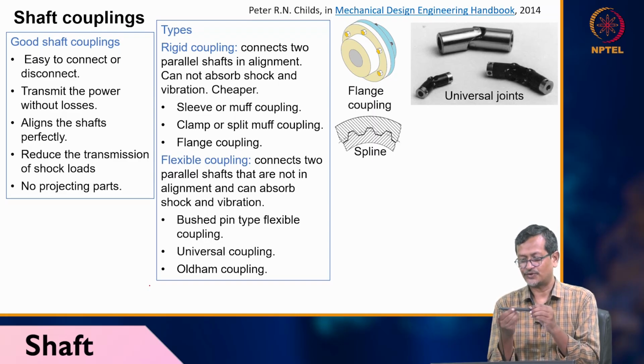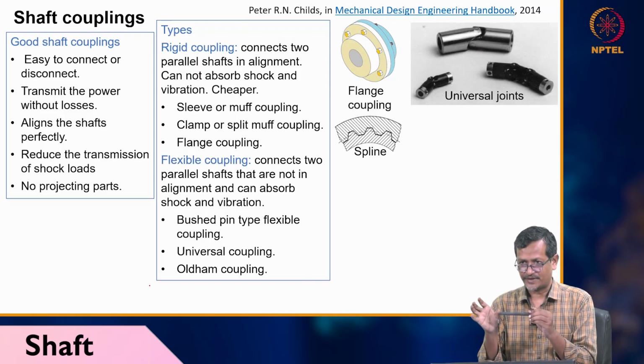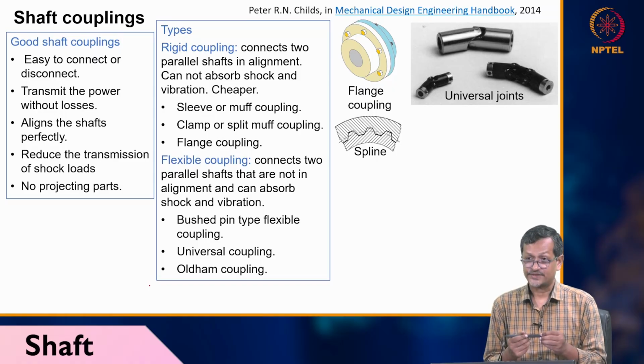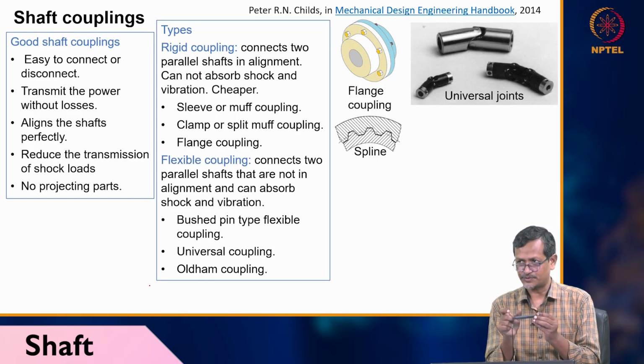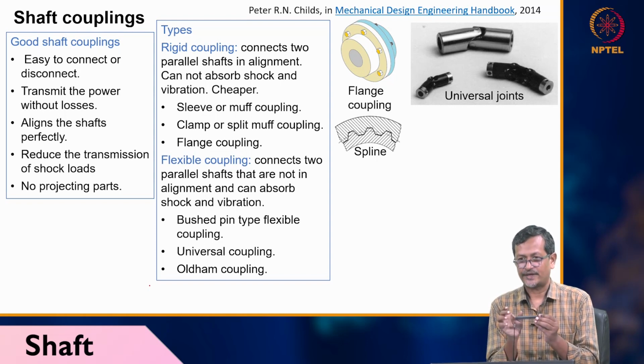That force should not go to your engine, because the engine produces only torque and will not take any extra force. It is not designed for that. So you have to transfer that axial force to your ship, so that the ship will move. That is called thrust. Whenever you transfer that thrust to the ship, you must have several small shafts: the propeller shaft or tail shaft, the intermediate shaft, and the engine shaft.